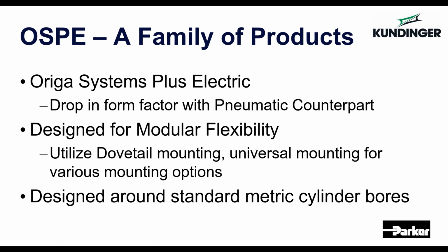So the OSPE stands for Origa System Plus Electric. If anyone's familiar with pneumatics, you're probably familiar with Origa. They developed these actuators around the time that Parker acquired Origa to be drop-in replacements for their pneumatic counterparts. So they're all designed around an ISO cylinder type bore, designed for modular flexibility as well. They're highly configurable, ordered down to the millimeter from a travel perspective, utilizing universal dovetail type mountings with a variety of available mounting options to suit your needs.